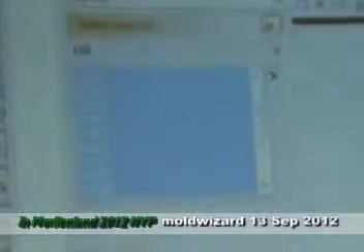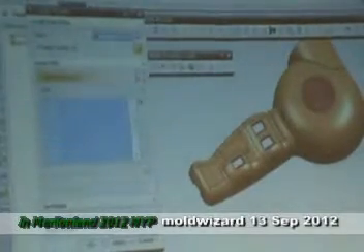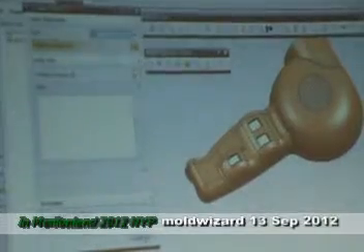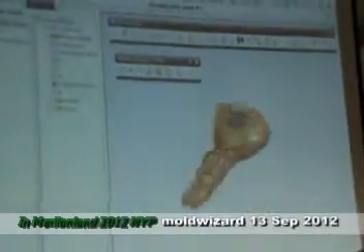So we just use auto patch. Select body. We now select. Okay, there. We just apply. Okay, already finished. So you can see so many surfaces are created for us. These are the surfaces. How much faster than the manual method.